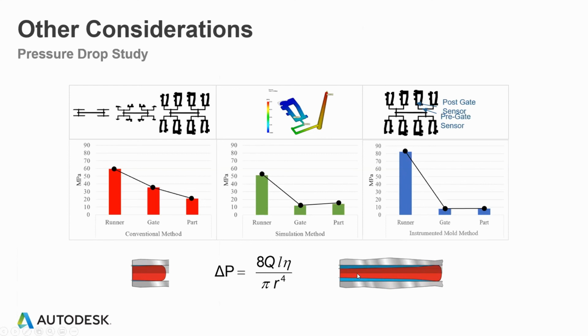So the only way to truly capture the pressure loss through, say, the sprue, the runner, or even the gates is to actually make that complete fill-only part, so that we can allow that frozen layer to develop. Then we've captured the pressure through the entire flow path. The step-back method doesn't capture that. So we have to be very careful there.